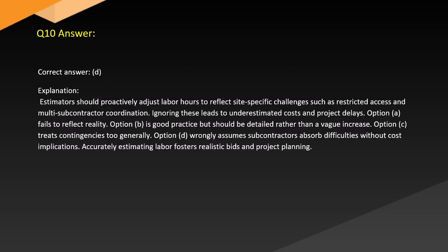Answer. Correct answer, D. Explanation. Estimators should proactively adjust labor hours to reflect site-specific challenges such as restricted access and multi-subcontractor coordination. Ignoring these leads to underestimated costs and project delays. Option A fails to reflect reality.